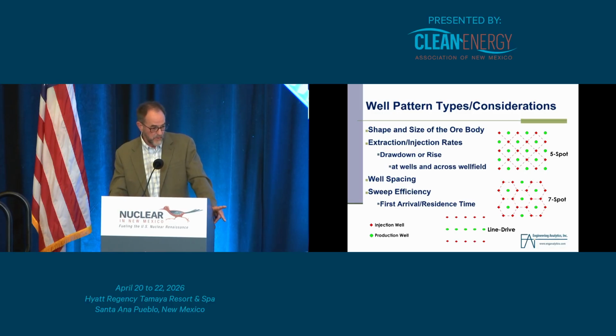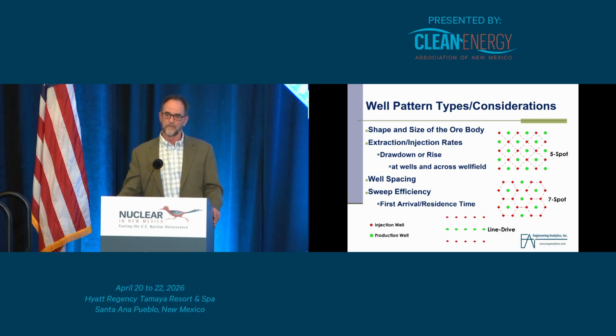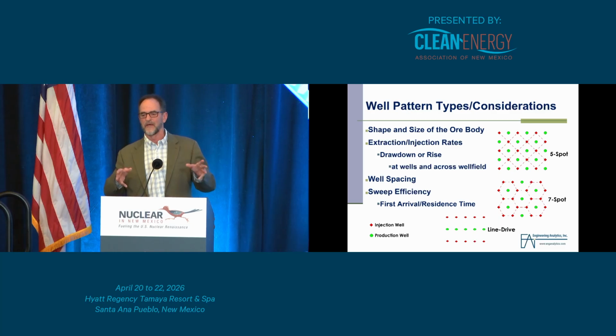Sweep efficiency: each one of these patterns has a little different sweep efficiency to it. So you might want to do test models and see how these different things work out under different spacings, different pumping rates. So again, modeling can help. It'd be nice if you had enough money, you could go out and do field experiments on every single one of these different systems and try and optimize your well field that way, but that's usually not very practical. So the modeling helps you quickly compare a lot of these variables and see what looks like it works best for the scenario or the site conditions that you have.